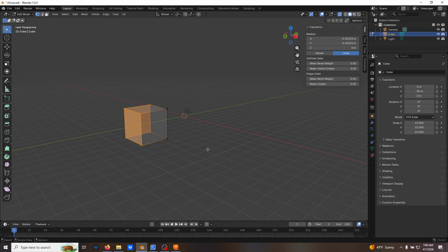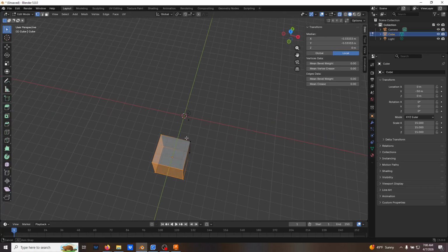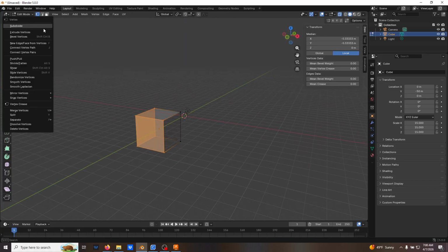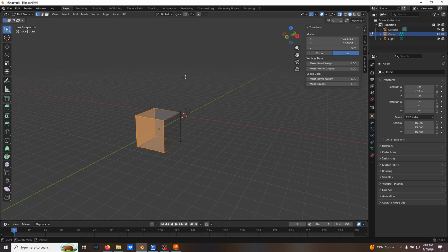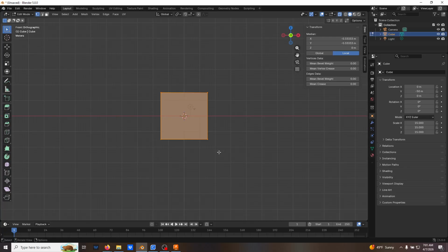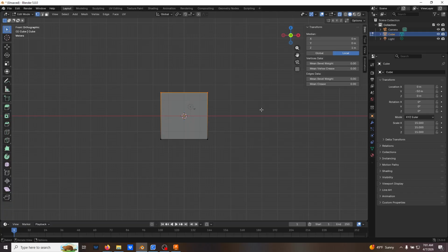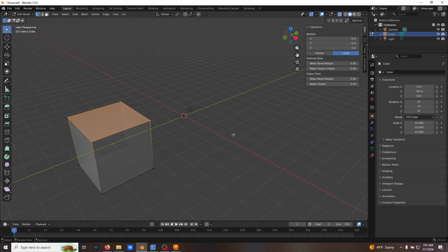Also, I'm a big believer in working with Blender with a keypad. So you can press 1, 3, or 7 on the keypad to go to your orthographic views, and you'll also notice that the perspective will change a little bit. Up here you'll see top orthographic, but when I rotate a little bit, it'll change to perspective, and that'll give you vanishing points on the lines. And sometimes when you're working, especially if you want to do your selections, going into orthographic mode with X-ray on will let you make selections like that.